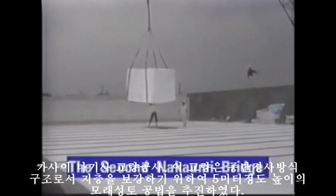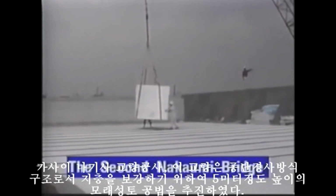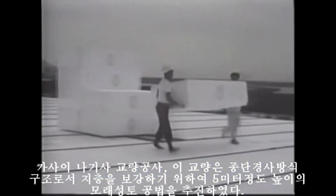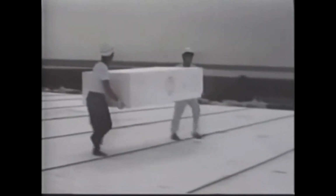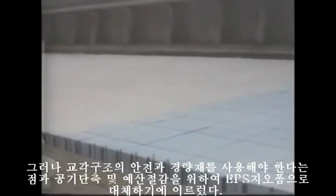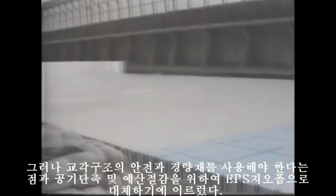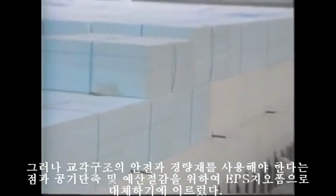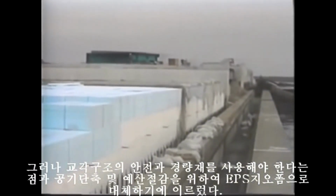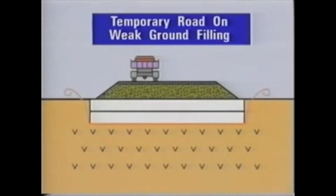For a similar reason, the EPS construction method has been used in connecting bridges, abutment backing, and filling for the waste disposal treatment sites at Tokyo Bay landfills. On this project, the top 20 inches of fill is extruded EPS foam material, and the balance is molded EPS. The combination of Geofoam fills provided both very lightweight material along with very high compressive resistance in response to the anticipated load.